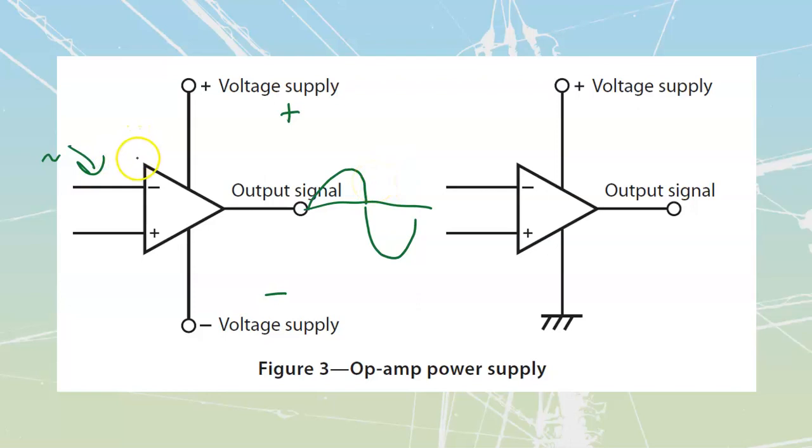Why do we want to do it through these? Well, just because in a lot of cases, the signal that's coming in is going to be a weak signal in the microamps. And if I try to run it directly through, that microamp signal is just going to get drowned out by the resistance of whatever it is trying to feed into. So we take the weak signal over here, we read it, and then we bump it up and we send it out into this output signal.